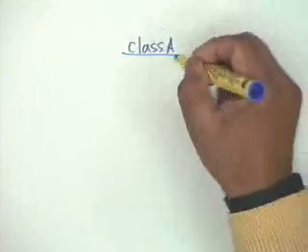What is so wrong about class A? Why not say class A? Class A has been used for voltage amplifiers, for current amplifiers, for small signal amplification. Why not for power amplification? I have told you the reason. What is the reason? At the Q point, there is a dissipation. Even if there is no signal, the current flows, and therefore there is a dissipation, and that causes inefficiency.